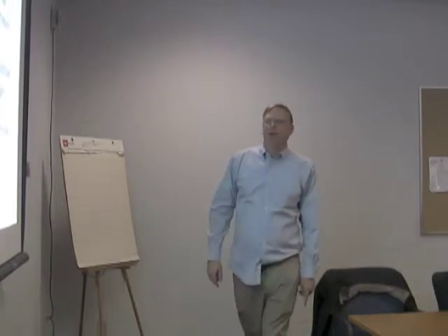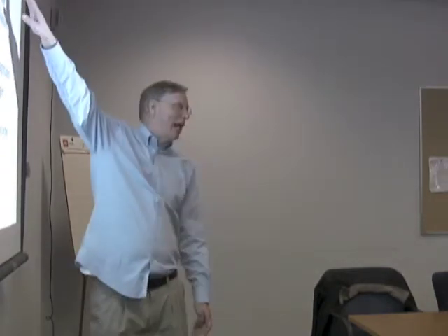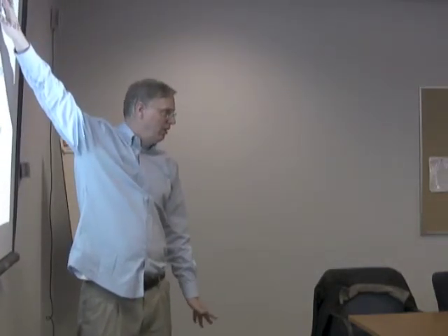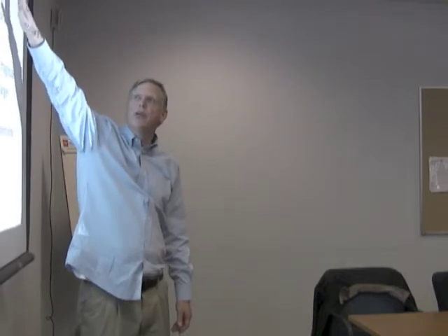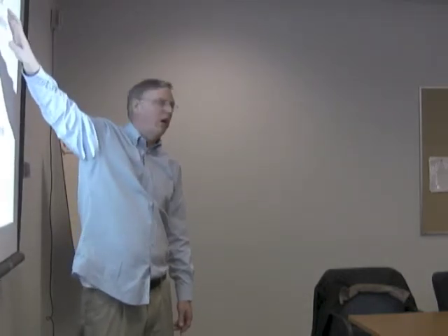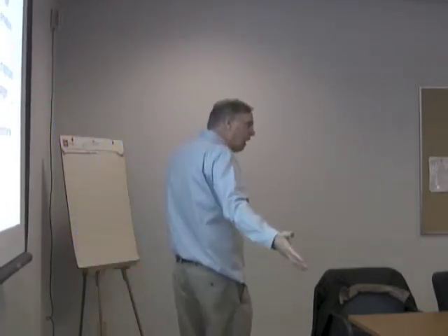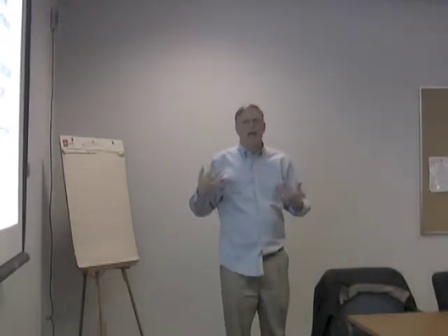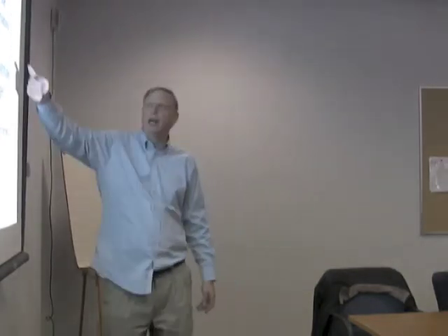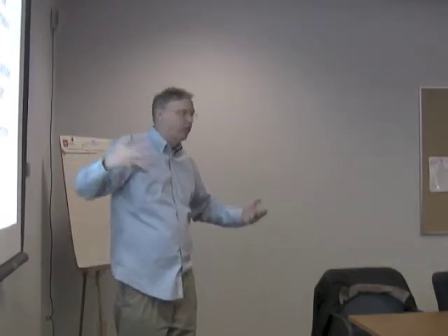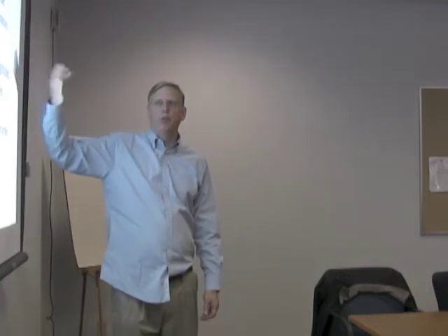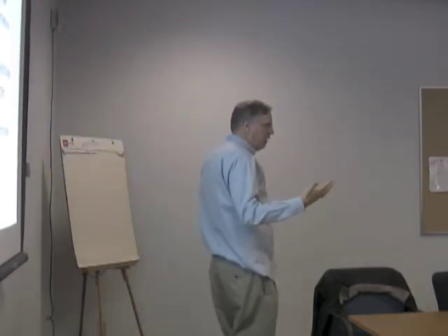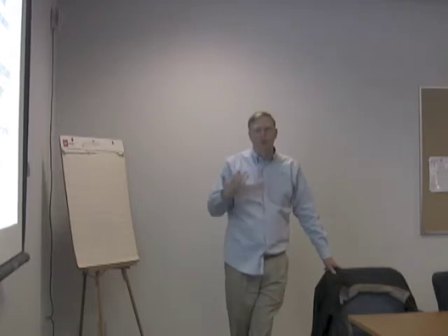Correct, and so the next one is for path terms. If we're going to get to 3D simulations, we need an applicable 3D velocity structure in the Central Coast region, and there hasn't been a good model developed. But it also requires validation, not of the arrival times, but of the amplification. That's what we care about, is amplification. So that has to have some ground motion data to be able to test parts of the model. Empirical data, again, will be limited to small earthquakes for path effects, because that's the only way we're going to get enough recordings to get at it.